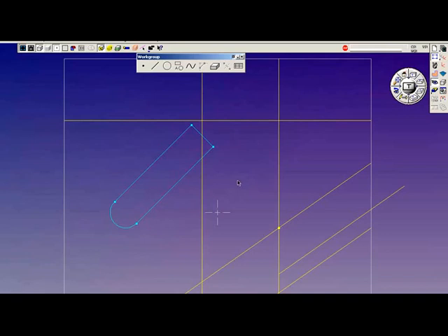Okay, another approach for connecting is hold the shift key. This will turn the cursor into an area drag marker. You drag this cursor with the shift key depressed over the intersection, release the mouse, and both features select. When using the shift drag method, any feature within the window will become selected.